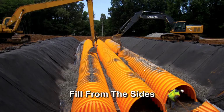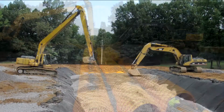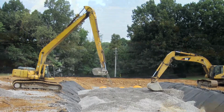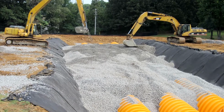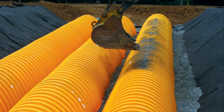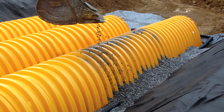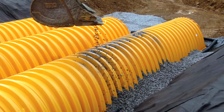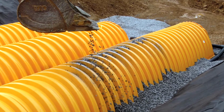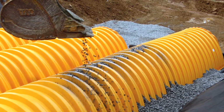With Method 3, the embedment stone is placed by equipment positioned outside of the excavation, usually a long boom hoe. The bed can be backfilled either after the entire chamber system has been assembled or as the chamber rows are being assembled. When placing stone by reaching across the rows, the operator must be careful to place stone on the crown to ensure even distribution on both sides of the chamber. In accordance with these three backfilling methods, never is it acceptable to place equipment on the bed.